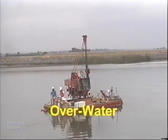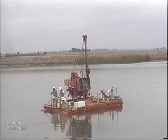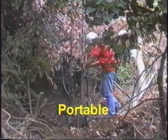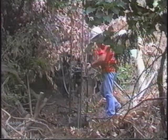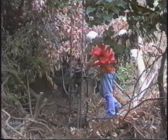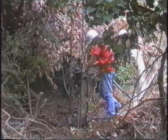For soil investigations beneath bodies of water, an overwater drill rig must be used. Some overwater rigs consist of a customized barge, where the drill rig is positioned in the center and drilling takes place through a hole in the deck. Portable rigs can be partially machine-operated, as shown here, or operated manually. These rigs typically have a depth limit of about 25 feet, depending on the subsurface conditions, and are used when access by an off-road rig is impossible and the expense of a helicopter is not justified.